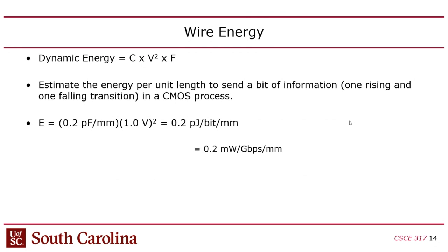So we have a couple of things we want to talk about before we finish up this low-level CMOS stuff. The first thing is really quick. It's energy. So I mentioned that there is static and dynamic power. Dynamic is from switching outputs of gates from 0 to 1, 1 to 0. Obviously, that's because during that time, both pull up and pull down go into saturation, and so they're both on, and you get a lot of current. There's also static power consumption, which is the leakage you get through the pull up and pull down networks, even when the gate is not switching.